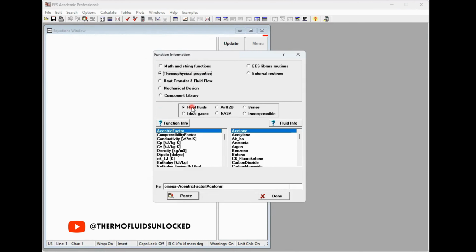If I want to simply define real fluids, they are fluids for which we do not have a specific, known equation of state relating P, V and T that we can easily use. So either we need to rely on thermodynamic tables or use EES to find the properties. For example, it could be a superheated vapor at a high pressure, a saturated mixture, or a compressed liquid.